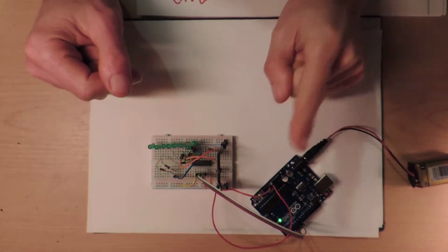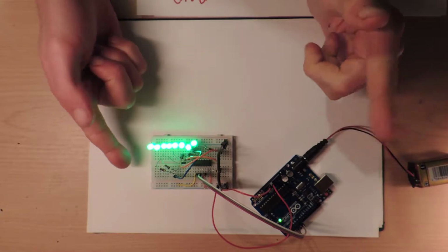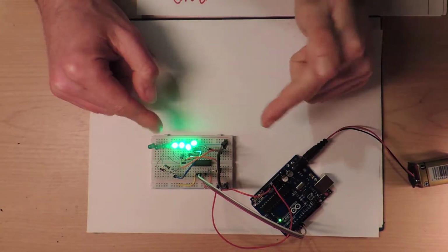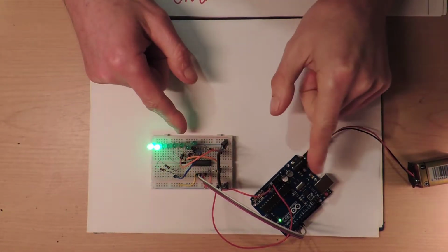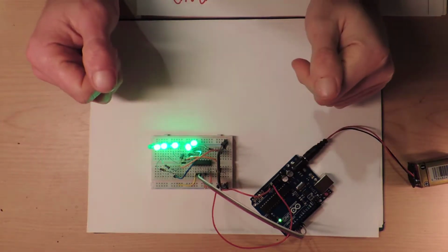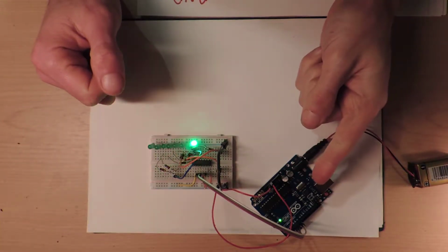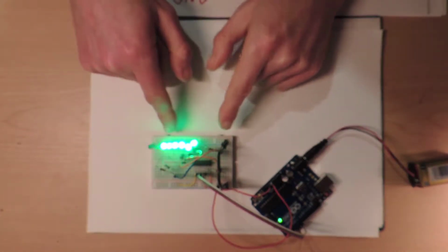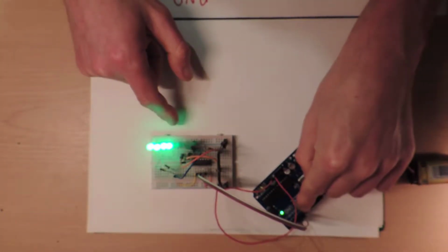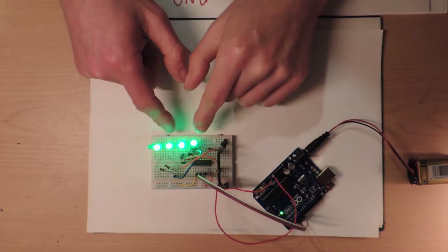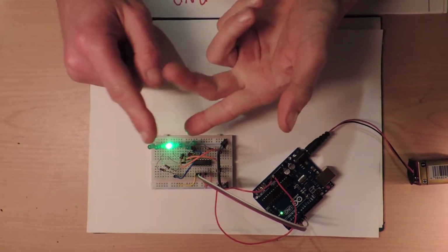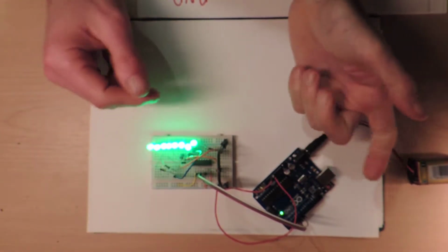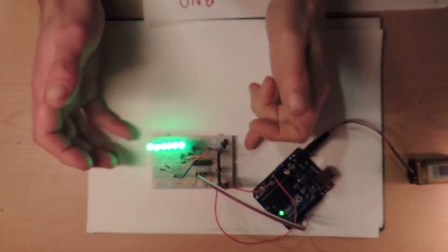The important thing here is we're using the 74HC595 from a few videos back, and I mentioned at one point that it's a useful IC for expanding the outputs on an Arduino. In fact, you can expand the inputs in a clever little way, but I'm not going to go into that today. But it's what we're using it for here. There are only 3 pins being used on the Arduino, these ones here, and they're connected up to the latch clock, the shift clock, and the data in on this IC, and that's what's doing all the work. So I mentioned doing that in the previous videos on this.